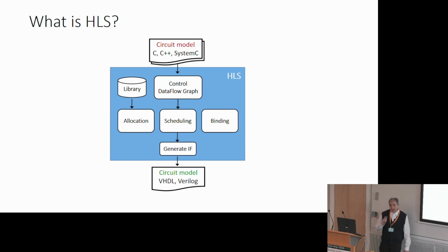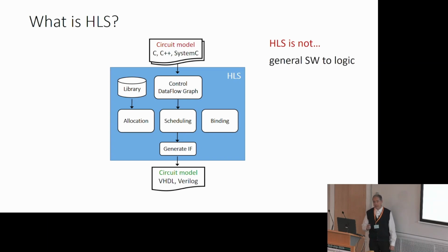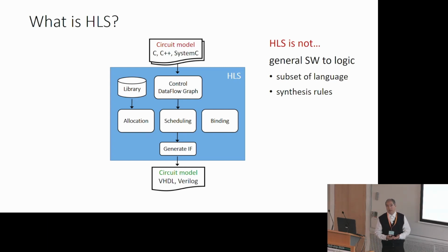Well, high-level synthesis is not general software to logic translation. We cannot take some arbitrary code in C language and convert it to logic directly, because we need to follow certain rules. Only a subset of the language is supported. And usually, code for software is designed and optimized to be run on a microprocessor, which is kind of different. We take a language syntax.